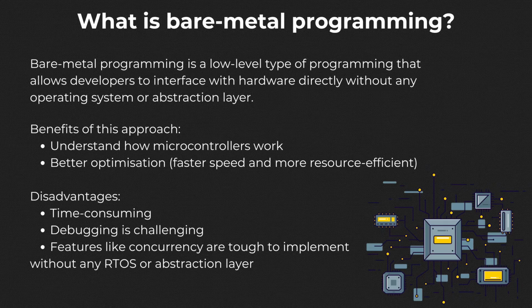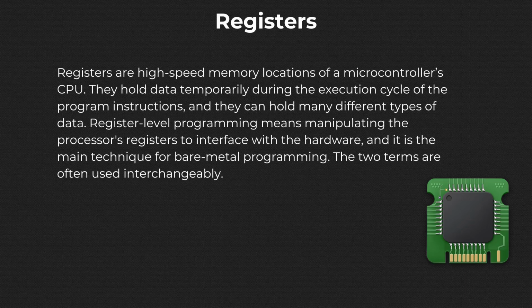Still, it is not practical to employ this practice all the time, as debugging bare metal code is very challenging. You have to write almost all device drivers for the system, which is time-consuming for large applications. Certain features, such as concurrency, are tough to implement without an RTOS.